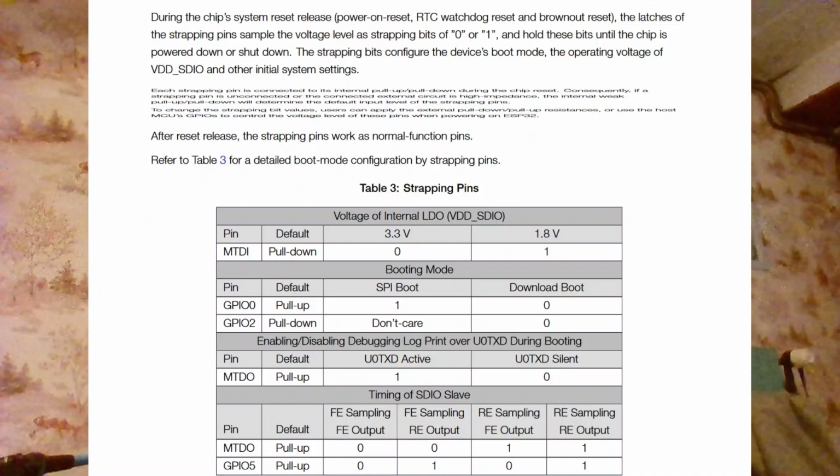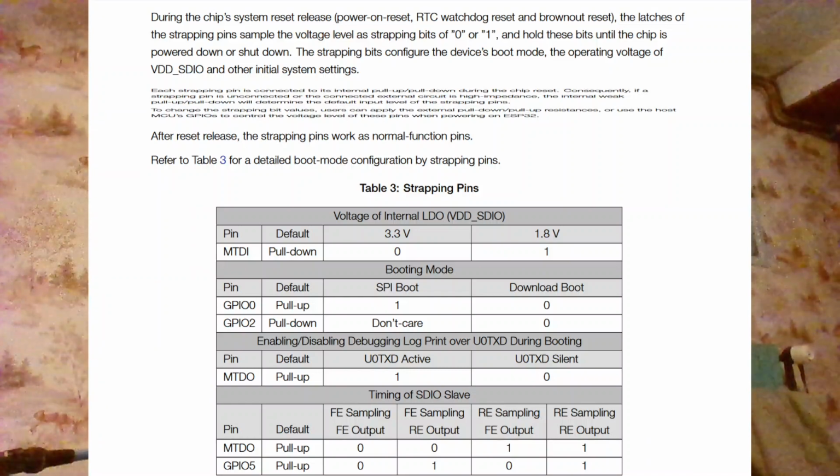And that means, if I'm right, that you have to send the firmware directly through the UART port. This is what you may want to do when you do some experiments without having to reflash the SPI flash.